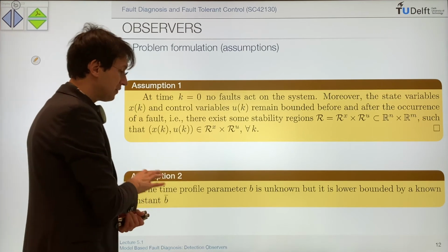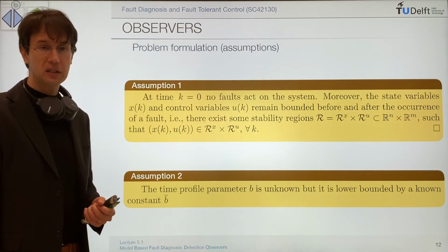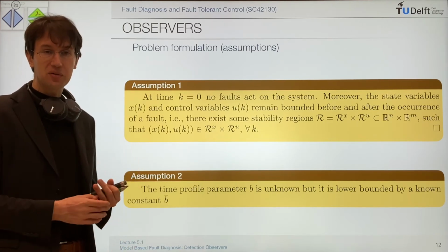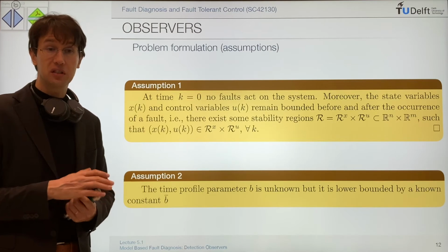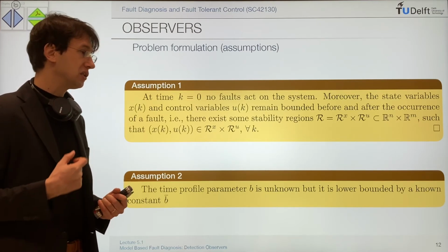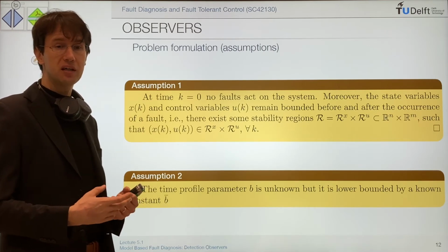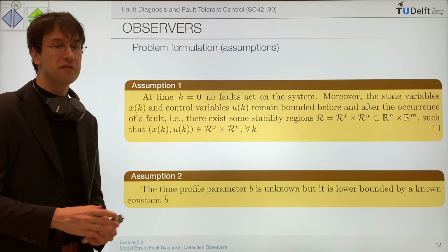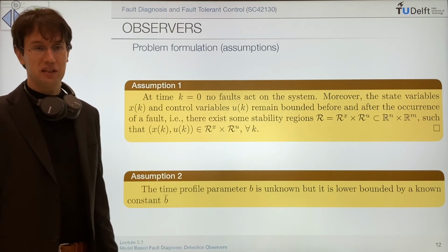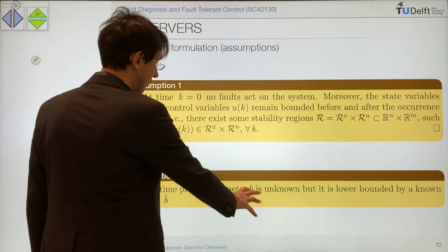And this kind of assumption, you see, they are going to occur a lot in the model-based approach, because in order to compute a threshold, in order to bound the residual, you need all the sources of uncertainty, the things that will make the residual big, of course, to be bounded. So if you have infinite uncertainty, okay, then your residual is going to be unbounded, and you cannot have a threshold. So this is the reason why we need these assumptions.